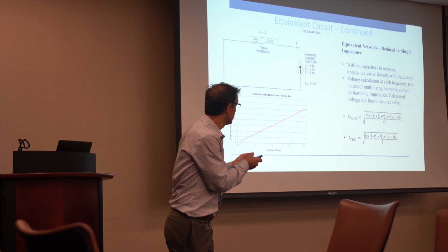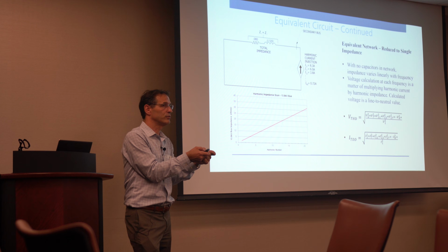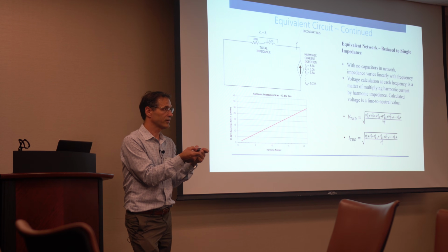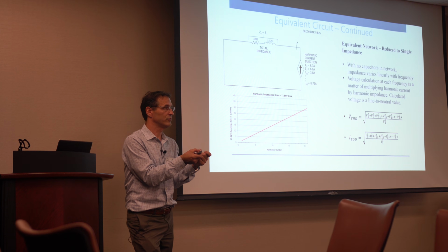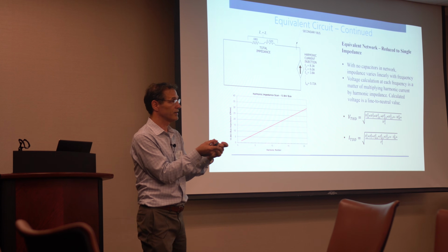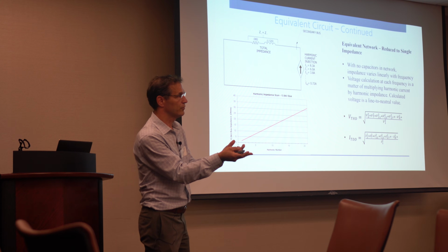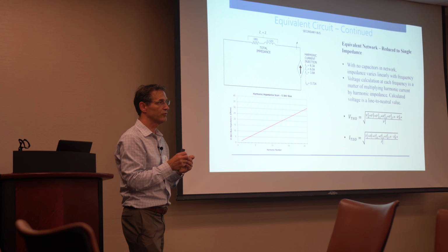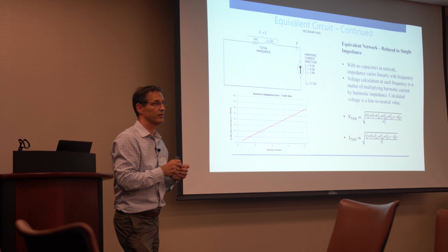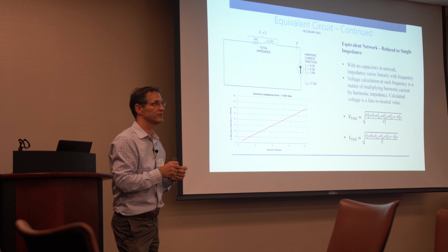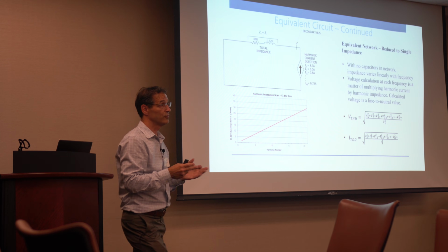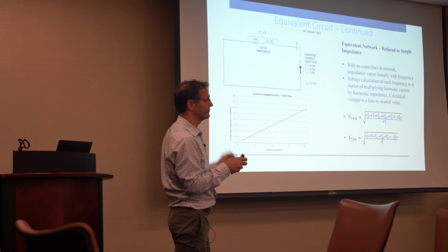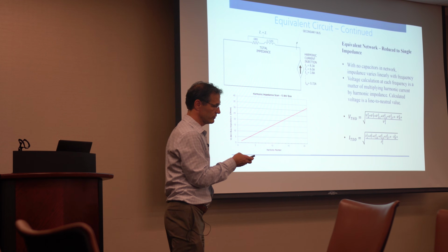Sometimes I have a customer who will say, I have X number of 6-pulse drives. I can take that value and say, well, what's your current? Right in the calculator, I'll do it on the phone with somebody. I'll say, what's your total horsepower connected? I can calculate the total 5th. What's your transformer impedance? And within 30 seconds, I've already calculated what your 5th harmonic current and harmonic voltage will be from that drive load. Very simple, without even opening a program. It's almost as simple as doing a simple calculation for a short circuit on a secondary bus. You can do the same here if you just know this basic principle.